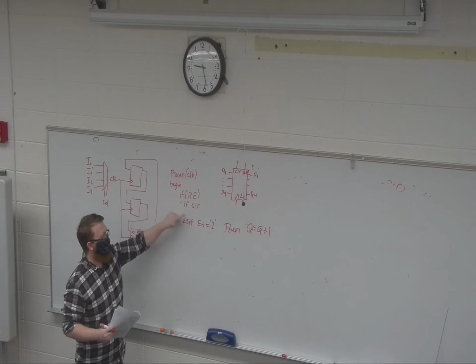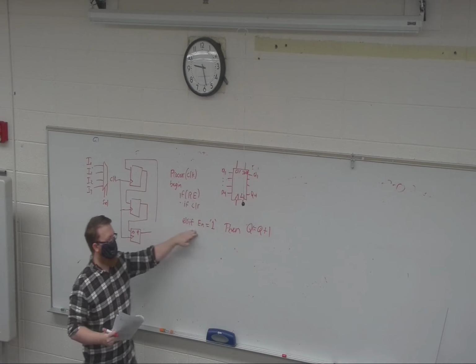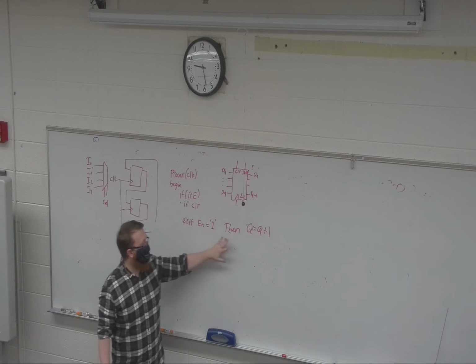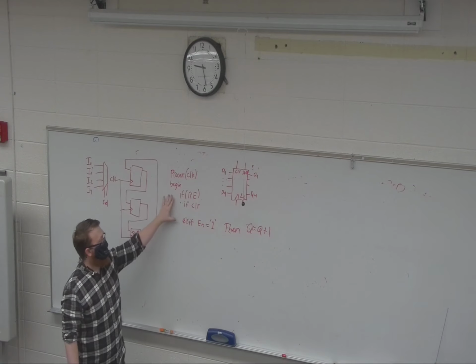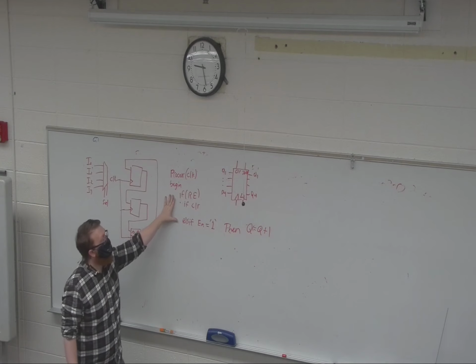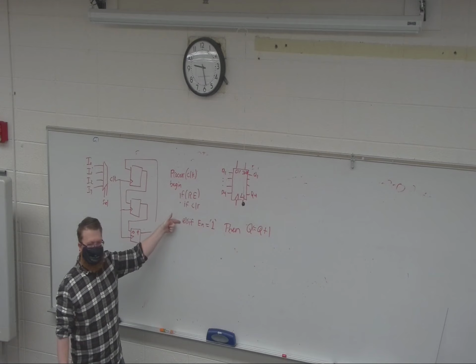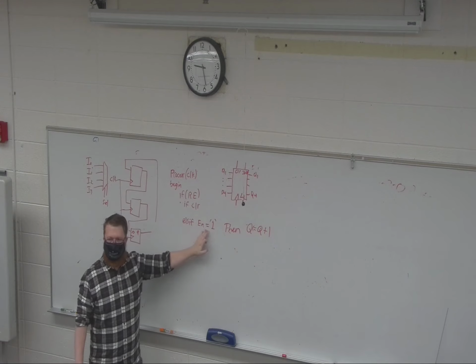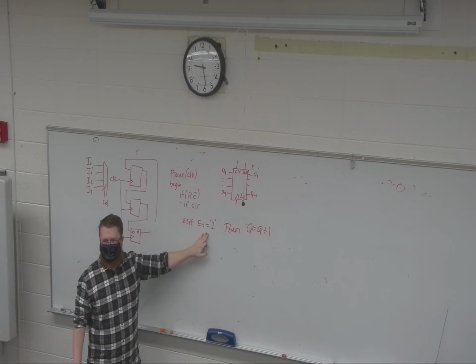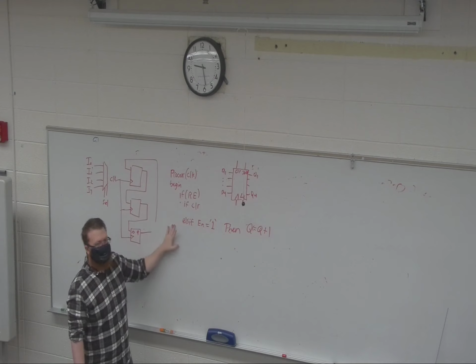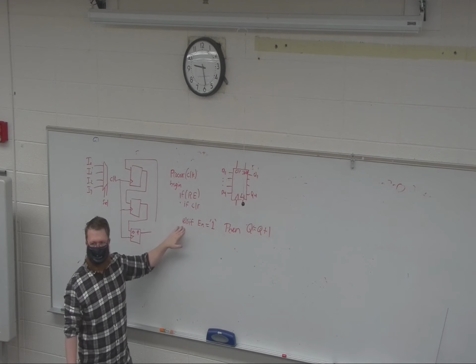If clear, go to 0. Else if enabled, start counting. This type of design is clock gated. So you'll notice the process executes every clock, but then only counts if enabled. So the clock enable architecture is really useful. Try and design your counters this way. Don't just say each clock count, do clock and enable.